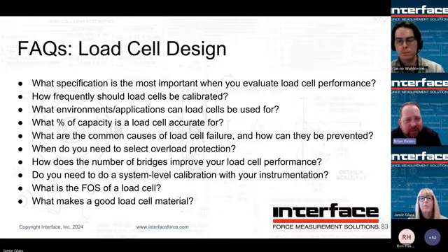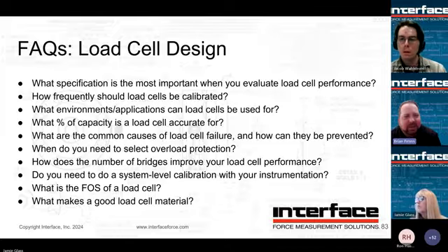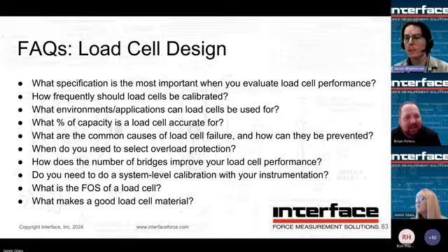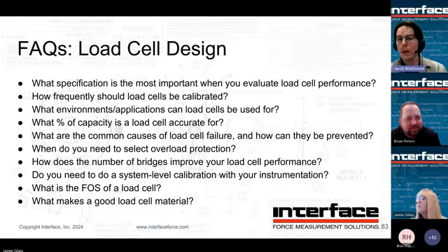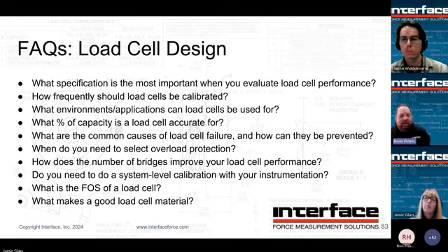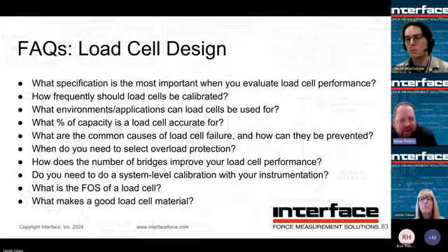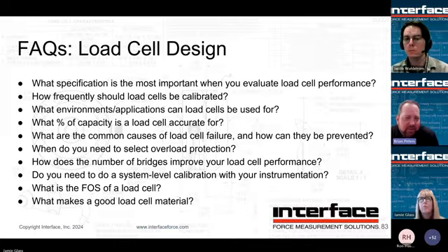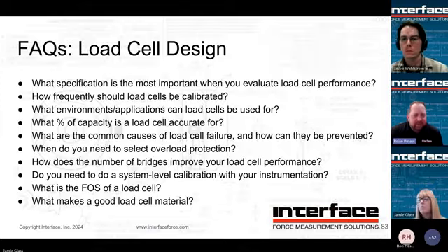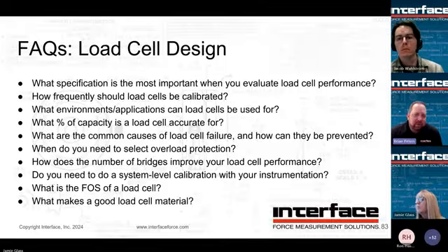So when should you select overload protection, or when do you need it? Basically, a lot of the minis have overload protection, and there's a reason for that, right? It's very easy to overload them, even by hand, if there weren't those overload protection features in there. Brian, you have anything there? Yeah, as capacity goes down, we typically try to offer it. It's necessary. But again, if you've got a test where you're interested in a certain cal range, a very tight test range, but then it still needs to see quite a bit of extra mechanical overage, then yeah, overload protection would be good.